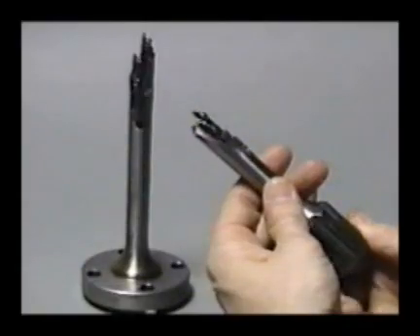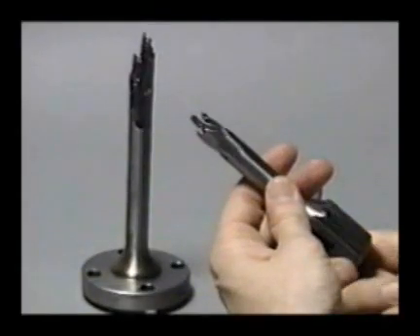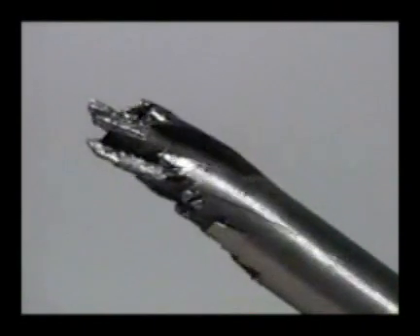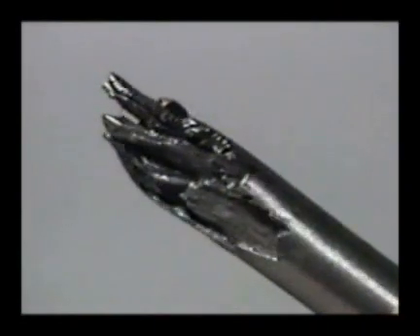Longitudinal shear fractures caused by torsion also start on the surface where shear stresses are highest and grow lengthwise and inward along the part, tearing grains along the way.